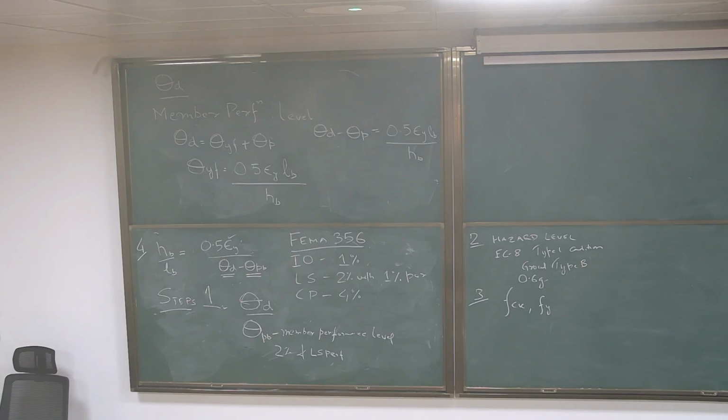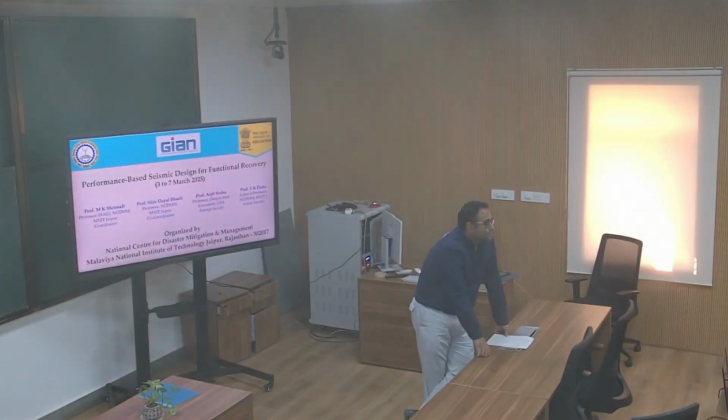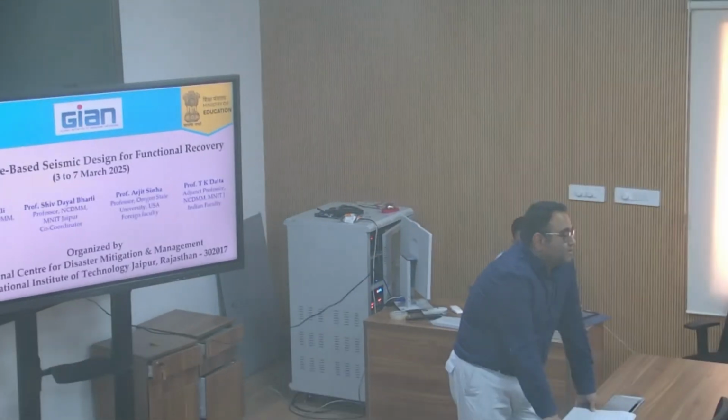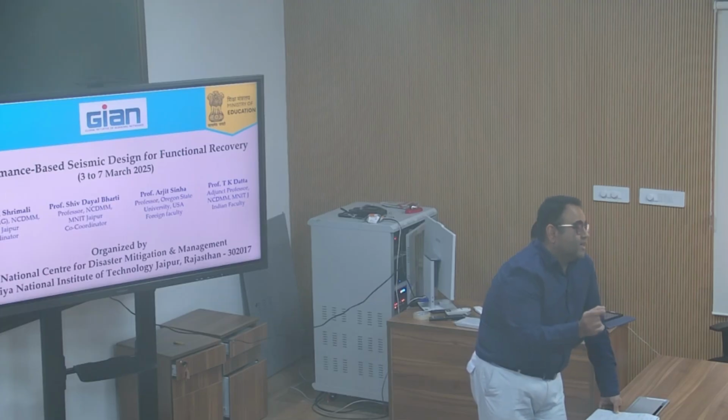Yes, but it is mainly a deformation state, and the deformation is governed by the steel. But when you're designing, you'll be using whatever the standard is. Sir, actually, it's a transformed section, but the M-phi curve is for both concrete and steel combined. Sure. So we have to consider both. At the end of the day, we are only taking epsilon y. That's why I'm asking. Yes, and that's what Priestley defined through empirical results as well as numerical models: the grade of the steel and the strain in it defines the deformation state much better than the grade of the concrete.